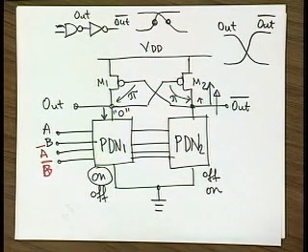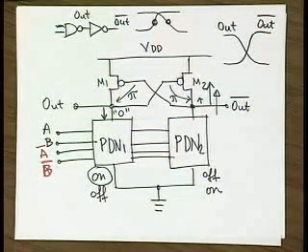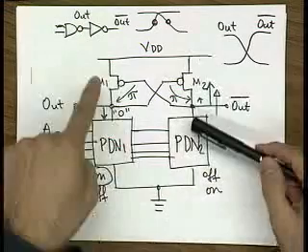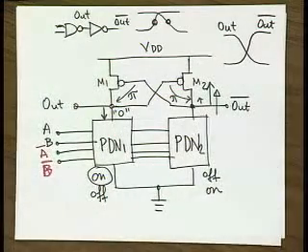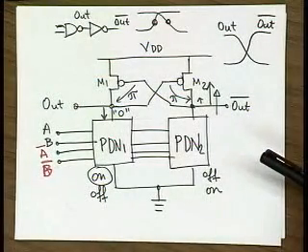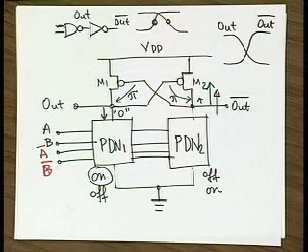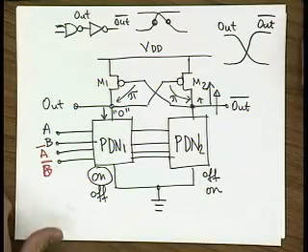VOL is equal to 0, and that means improved noise margins, and there is also no DC static current at the steady state. You do have some extra current when you're fighting this feedback and switching, but that's just extra switching power that you need to spend. But at the same time, you implement two functions, true and complementary. Okay? Questions?